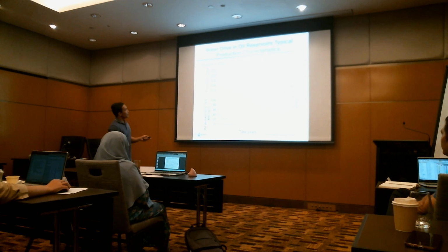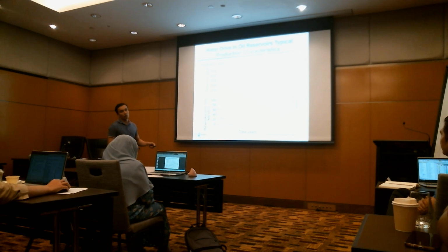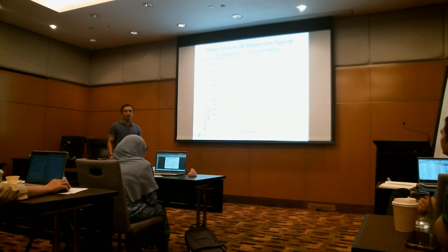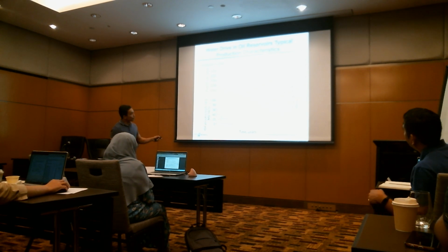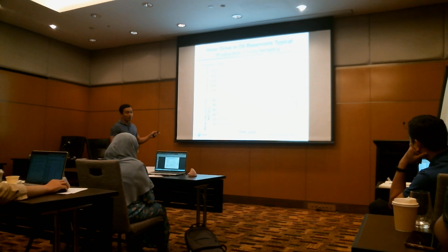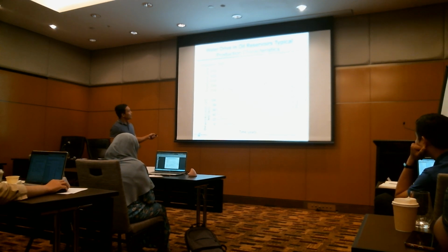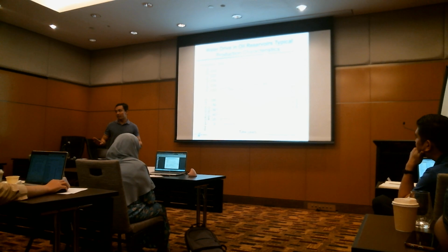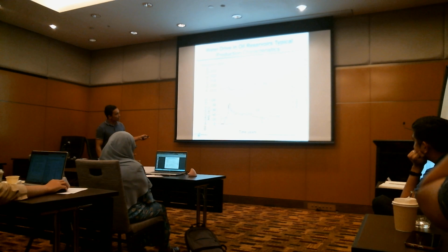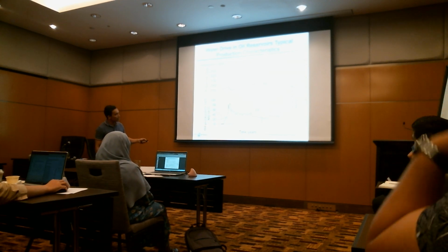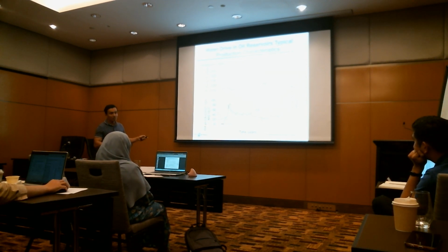Okay, this is the reservoir performance. For reservoir pressure, you see the pressure still declines. Of course, you have to decline the pressure, otherwise how do you get water into the reservoir? But the main highlight here is that the pressure is pretty much constant, it's stable. Gas oil ratio, like mentioned, you expect it's more or less maintained at the Rsi. For the oil, you can see that it's much gentler. You have a peak, and then it's gentle because the reservoir pressure is pretty much maintained.